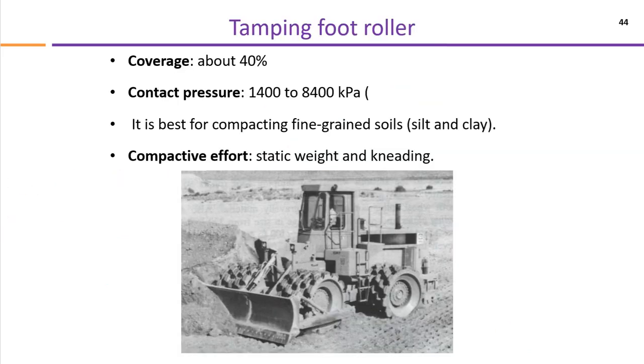Now there is another roller which is called tamping foot roller, and it is same as sheep foot roller, but the only thing is these projections are going to be big. So these projections here, they are big. So the coverage is 40%. It is not 10%, 40%. And the pressure, it can exert up to 8,000 kilopascal. Again, it is used for